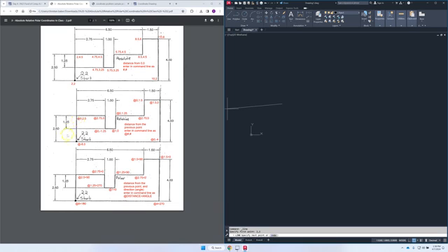So our y value needs to change in a positive 2.5. So with a relative input, you would type in the @ symbol, the change in x, which was 0, and the change in y, which is 2.5. So I'll type that in, @ 0, 2.5. And hopefully that drew a line straight, 2.5 long.